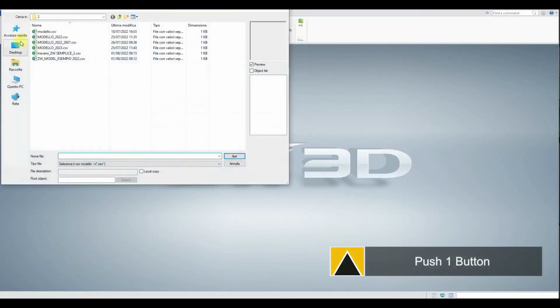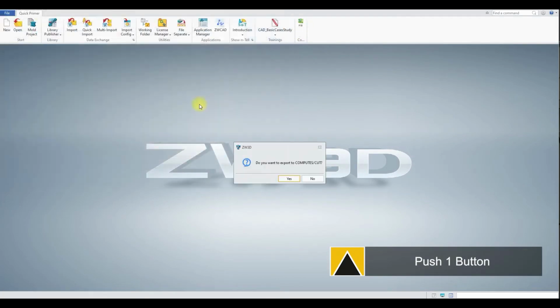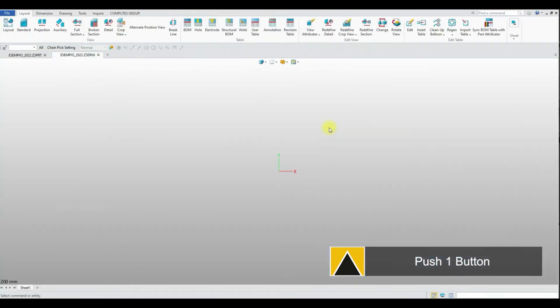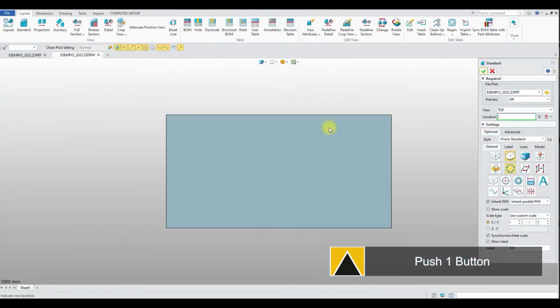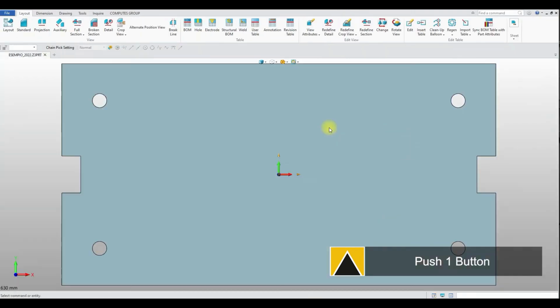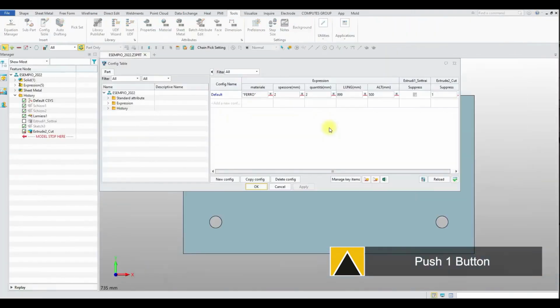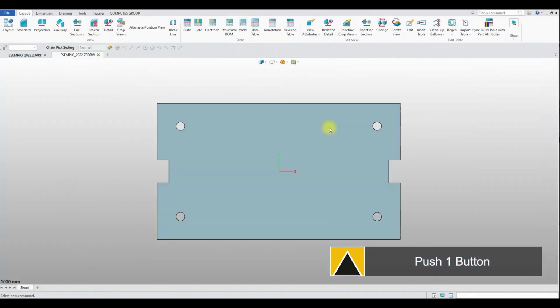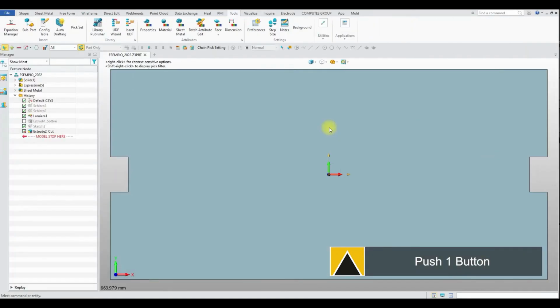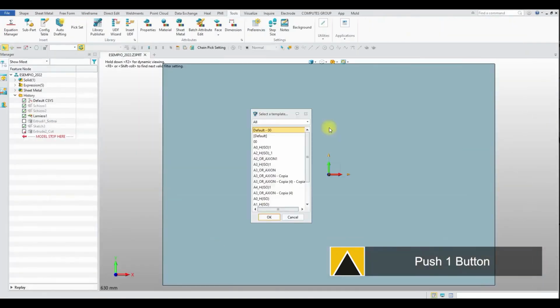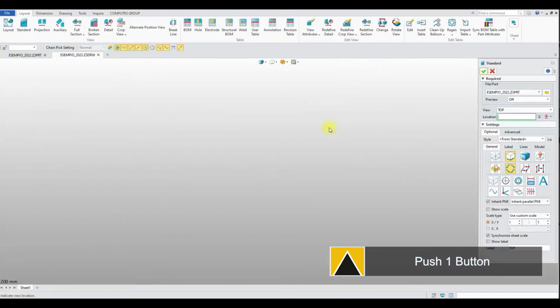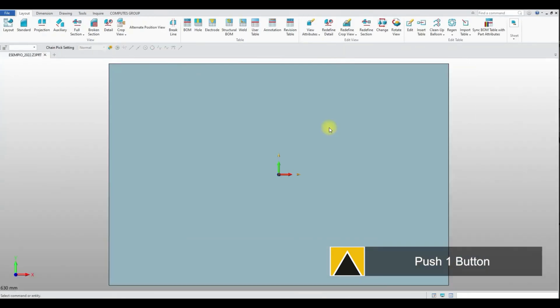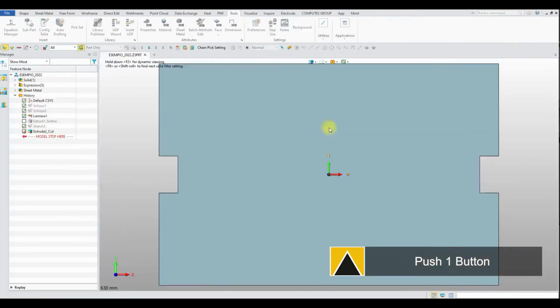Presentation: the macro P1B. This macro, in order to work, needs a 3D parametric part and a CSV file that contains one or more configurations for the model. The Excel file can be saved, for example, from your ERP. Each configuration is a row and can contain more parameters. These correspond to the variables of the 3D model. This macro will create a different DXF for each row with the correct parameters. The first row of the Excel file is not used data, but it only contains the name of the variables.